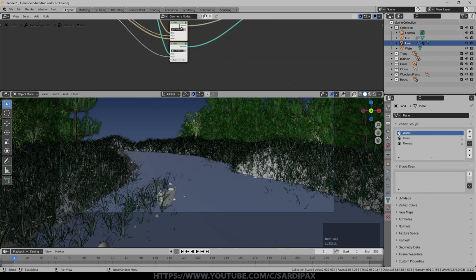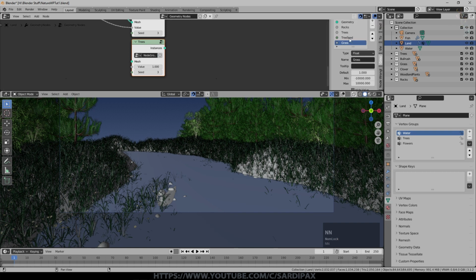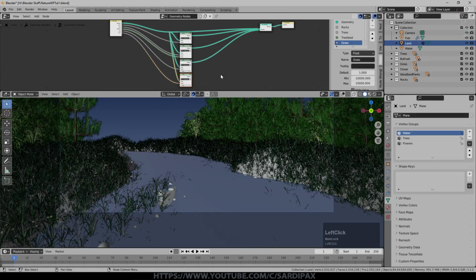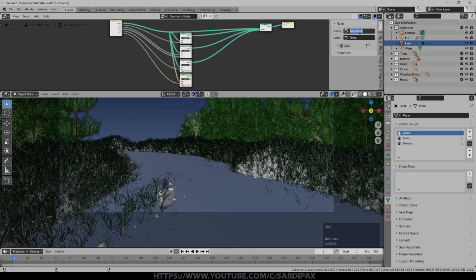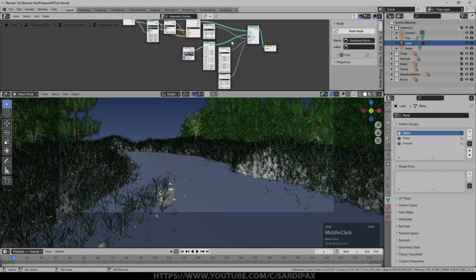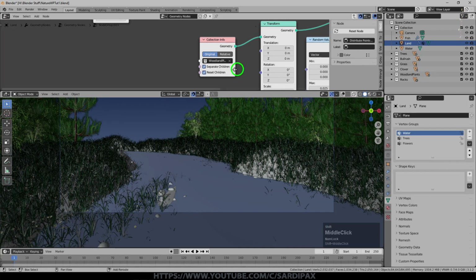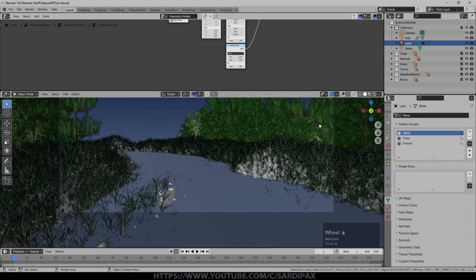So we'll select our trees again. Again, remember to click that little 2, press N to bring up the options for it, connect it into the geometry and connect it as it were to the outside world. We'll call this one flowers, and then we'll go into it and we'll change this to woodland plants. I haven't added the clover into the grass either, but that's easily done.